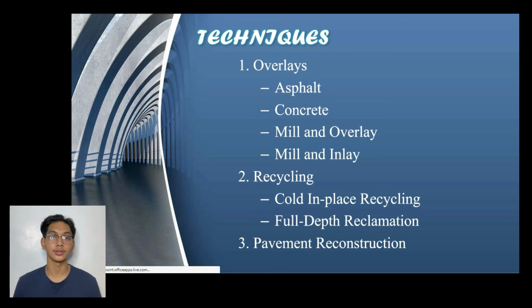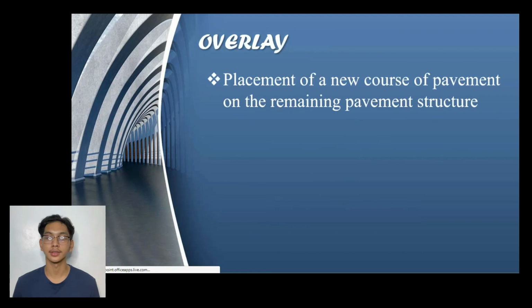Pavement rehabilitation also has different techniques. One of these is the overlays, which includes asphalt, concrete, mill and overlay, mill and inlay. Second technique is recycling. First way of this is the cold in-place recycling, and another way is full depth reclamation. The third technique is the pavement reconstruction. Now let's talk about it one by one. Now the first technique is the overlay.